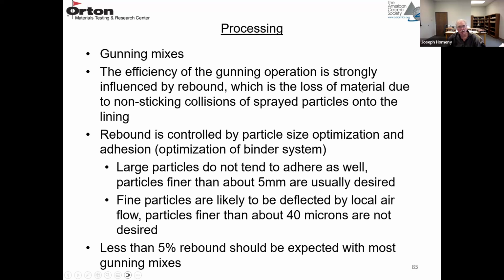And again, the rebound is just material that bounces off the wall or the ceiling. So it's lost material due to non-sticking collisions of the sprayed particles on the lining. Rebound is controlled by the particle size and the adhesion by optimizing the binder system.